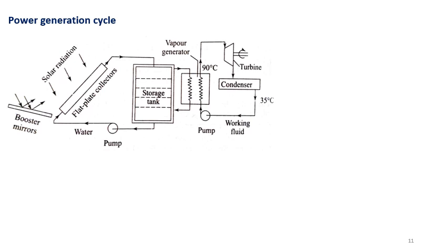So solar energy absorbed in the central receiver is removed as heat by means of heat transport fluid and converted into electrical energy. In a distributed type system, which may consist of a number of parabolic trough type or line focusing collectors, or a paraboloid dish type, which is point focusing collectors.